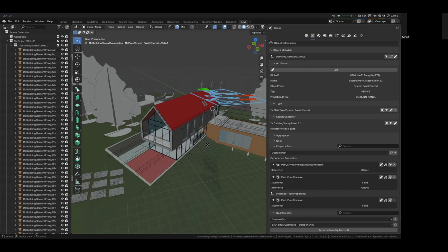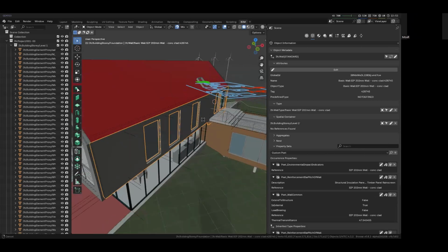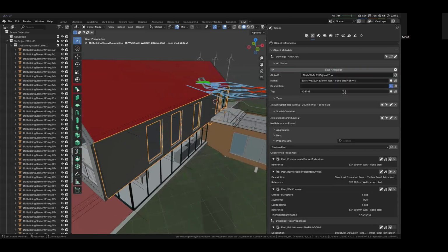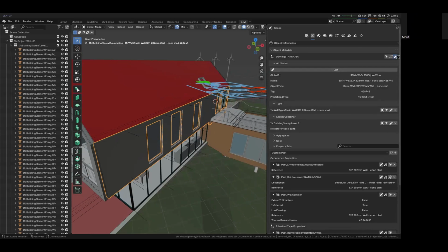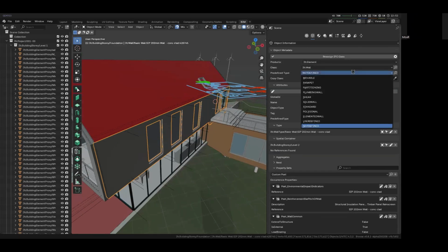Now, I guess in hindsight, people realized that was not such a great idea, that the classification should be more about the function of the object, not the shape of the object. So IFC went through this purge of the second level of classification, where for the few anomalies which refer to things like the shape of the object, they started removing them. So for example, if I go and edit the second level definition of a wall, you'll see some pretty strange things.